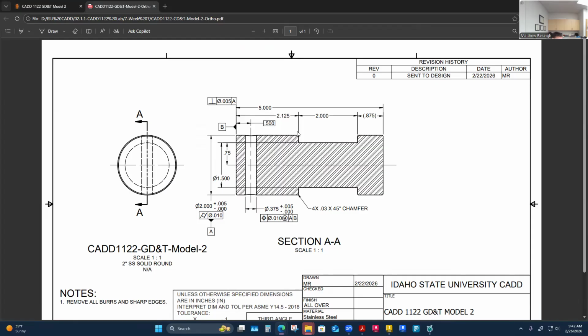I'll pull this up on my other screen, just draw this little profile, 2 1/8 comes down. I think it comes down a quarter. I'll dimension it this way. You can see my dimensions are kind of driving from the datums that we've established. But if I just look at the profile, we can worry about datums in just a minute, or look at them a little bit now.